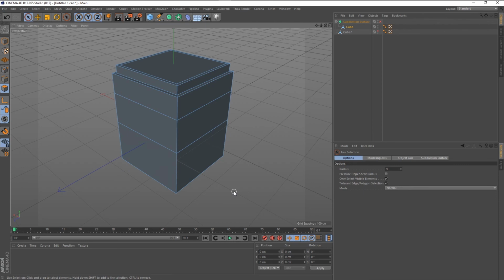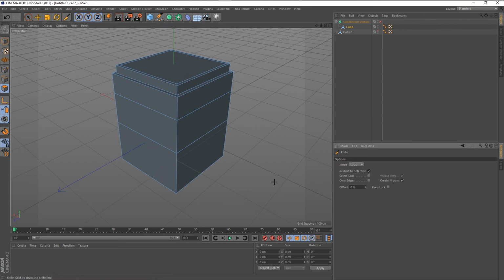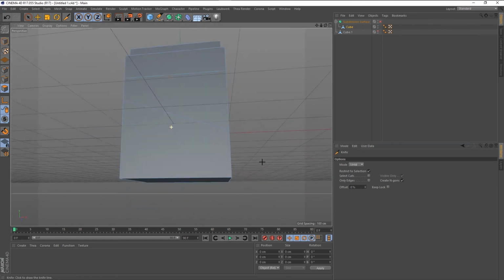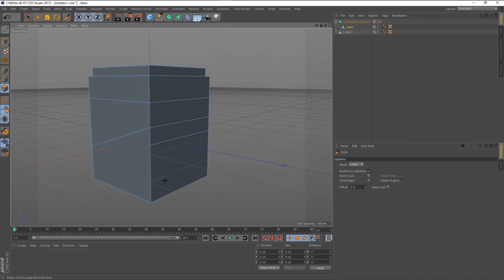Now if I don't have anything selected, I hit double K for a loop select. It's still in loop mode like it was before. And now if I click on that, let's see what it does. Ooh, that is weird. Why is it doing that? Oh, that's because it went from this relative position on that edge to the same relative position but on this bigger edge. So I'm going to hit Control Z a couple of times here and get back into...